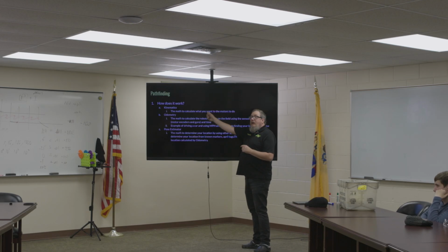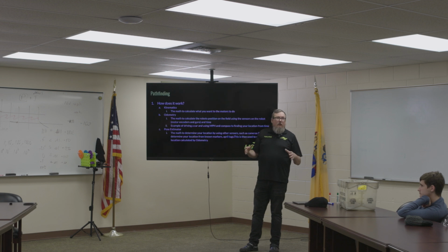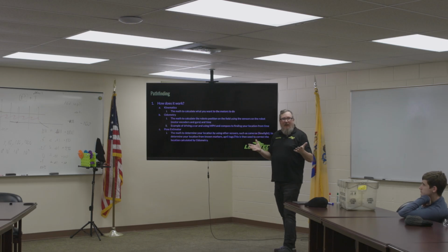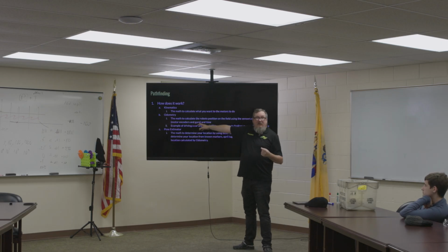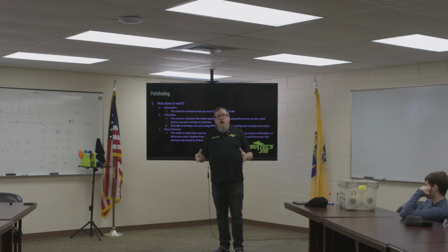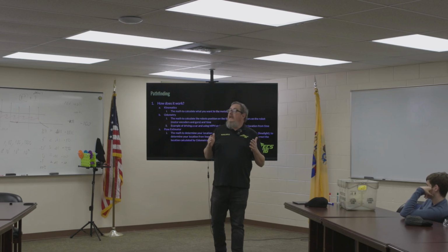Odometry. While kinematics will give you the path and the plan that you're going to follow, what's the saying? Any good plan that's made in war falls apart once the battle starts. There's something to that effect. That's where odometry comes in. Odometry is measuring where you believe the robot is based on the movement that it has done.